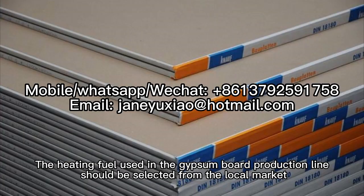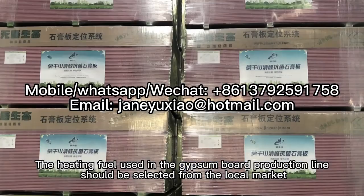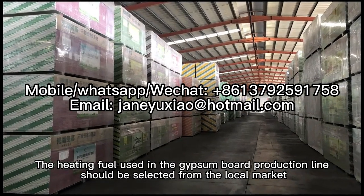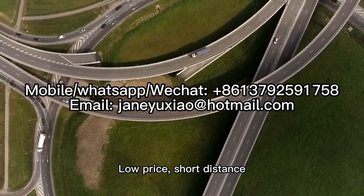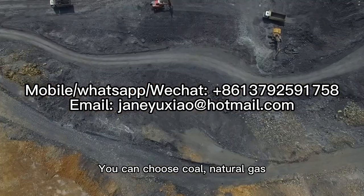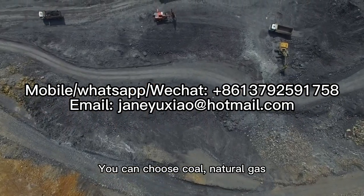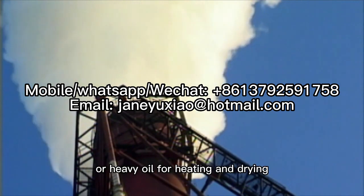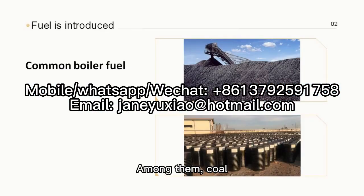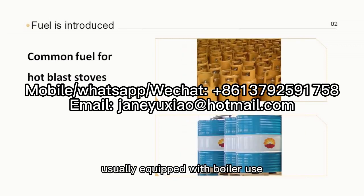The heating fuel used in the gypsum board production line should be selected from the local market. Low price, short distance, and convenient transportation are the first choice. You can choose coal, natural gas, diesel oil, or heavy oil for heating and drying. Among them, coal and heavy oil are usually equipped with a boiler, while natural gas and diesel are equipped with a hot blast stove.